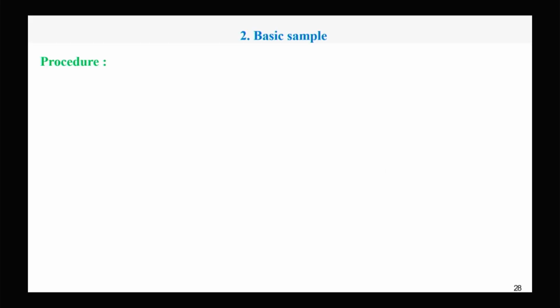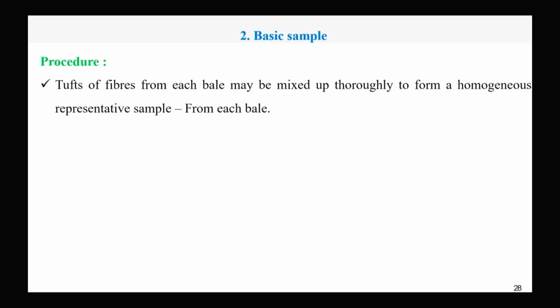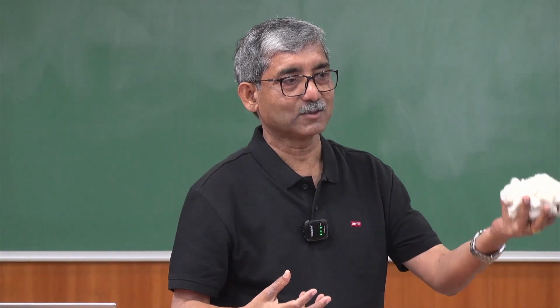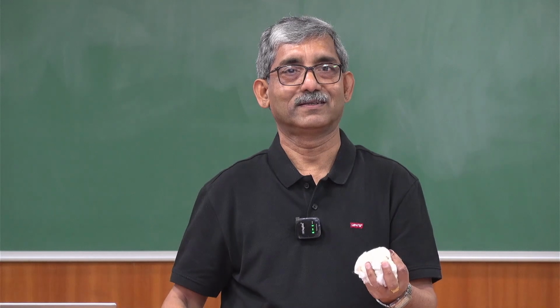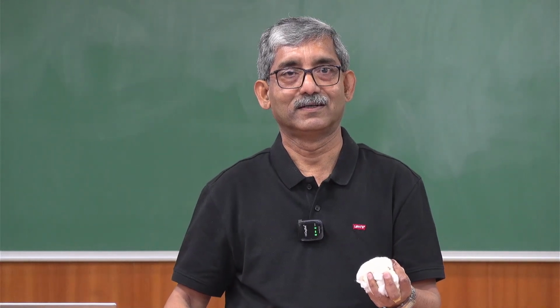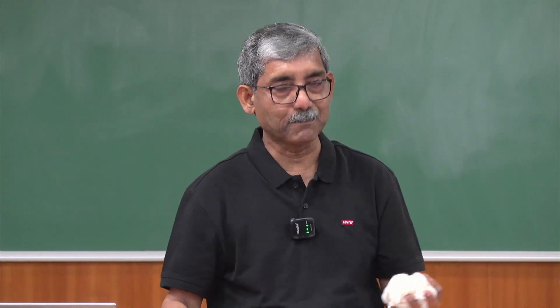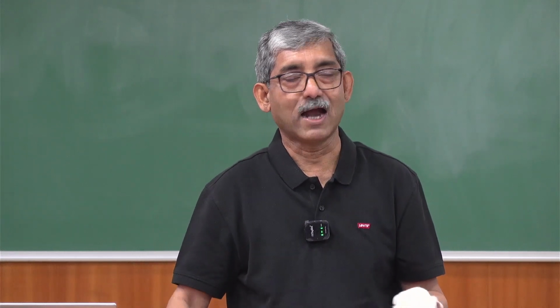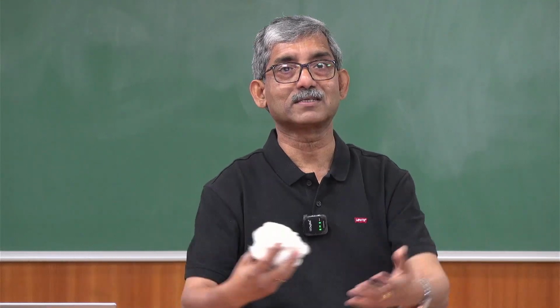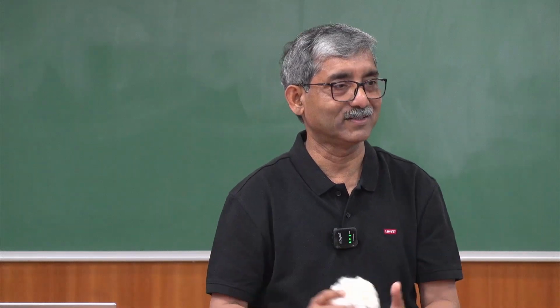Then the basic sample: from each selected bale we will select a small quantity, and then we will mix thoroughly, and a proper homogeneous sample has to be prepared, and the total quantity of this basic sample should be around 1 kg.